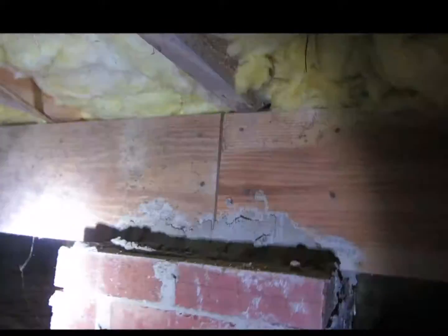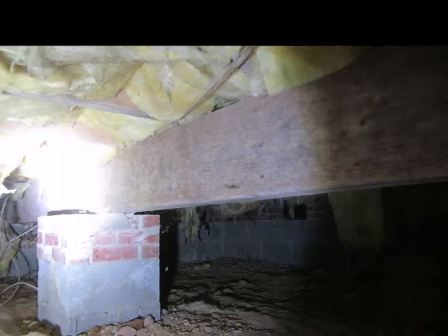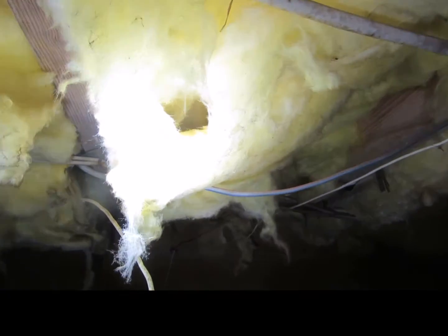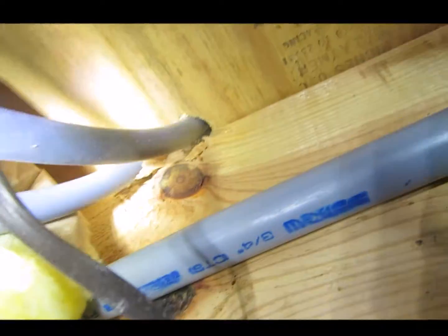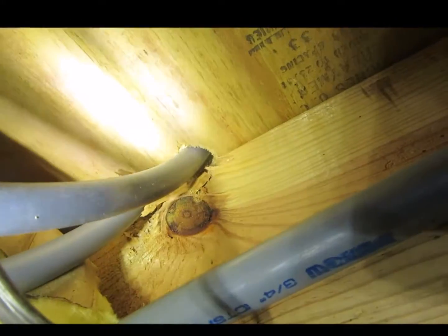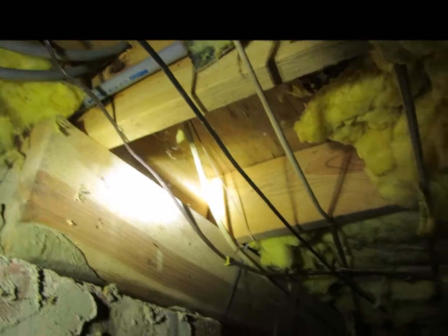And then here's a type that's growing on the main beam. This crawl space has signs of rodents. We have these nice round holes that are burrowed into the insulation, so another reason why it's falling down. And in areas where there is exposed wood, you have mold growth, and since the penetrations in the subfloor are not sealed, you have access for the crawl space mold and insects to go into the home.